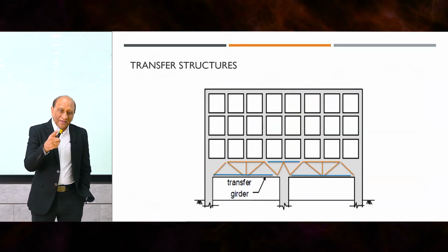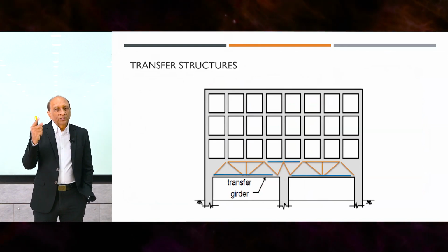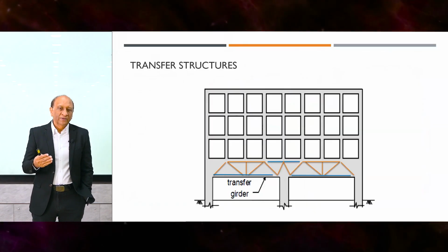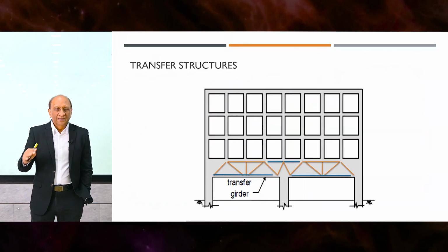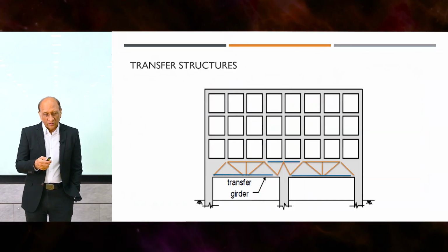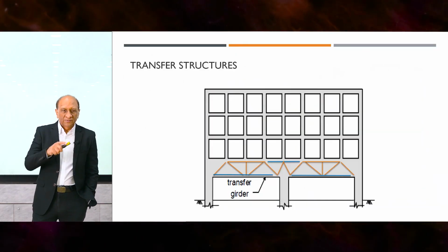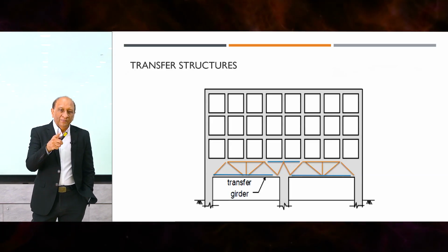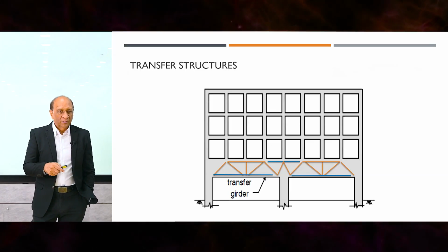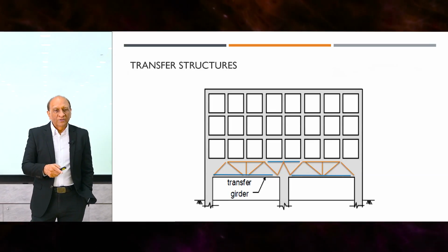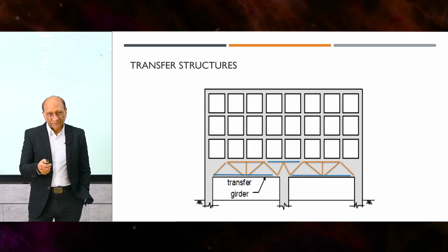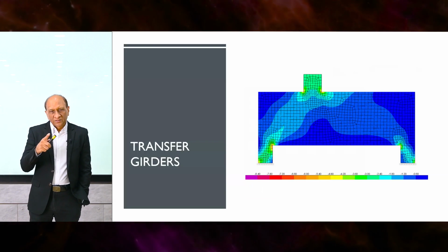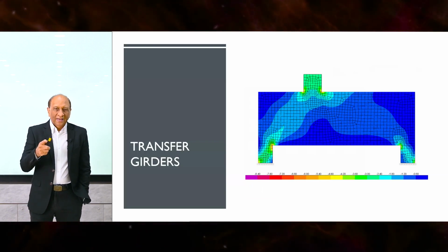And in many buildings, architects prefer to actually show these trusses directly in steel or in concrete because it looks very nice to transfer the load by direct inclined struts or columns and make a truss there with a space open with the glass or whatever. So many buildings tend to do that also because you really don't need the concrete between the triangles. And once again, the transfer girder stresses can be checked by finite element analysis, and then this can be used